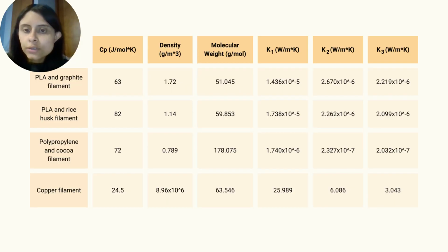After the different graphs were analyzed, it was possible to obtain an experimental value of the thermal conductivity of the different composite materials. These results also describe and confirm the fact that the materials are anisotropic. This is because in each of the different regions the conductivity varies. It is also shown how the closer the region is to the heat plate, the bigger the conductivity is.